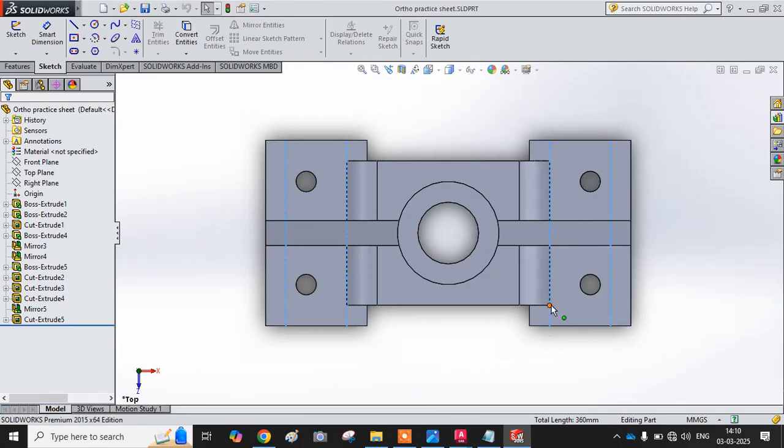See, again I am repeating. From here to here, from this point to this point, कैसे आएगा line? Hidden, because that edge is underneath. Then from this point to this point, dark, because this edge is visible from the top. Then from here to here, inside the rib, hidden. From this point to this point, dark. And from this point to this point again, hidden. देखो एक ही लाइन में इतना variety आ रहा है. Okay, same way on this side also. But these two lines are completely hidden.